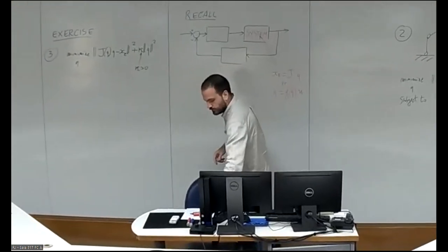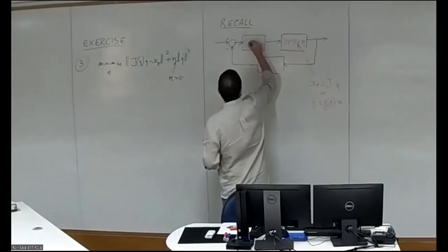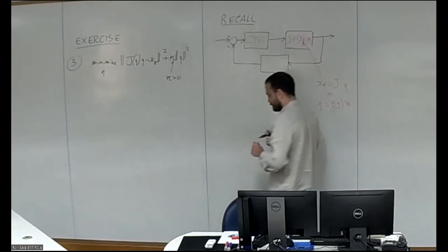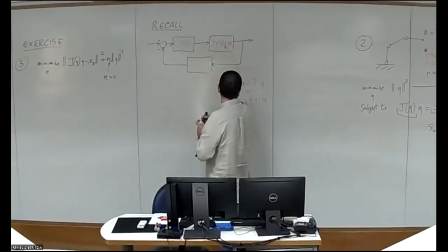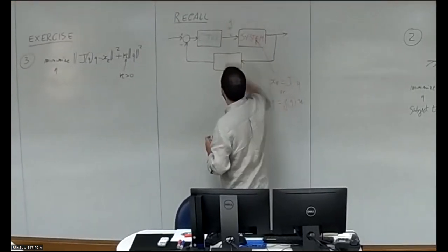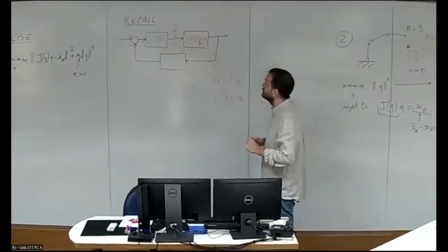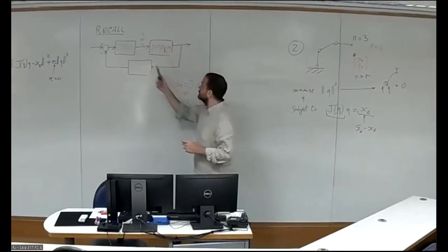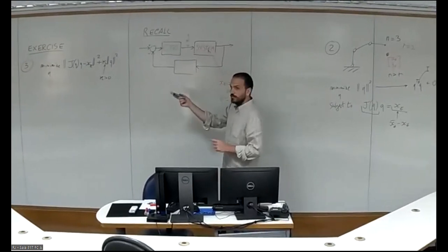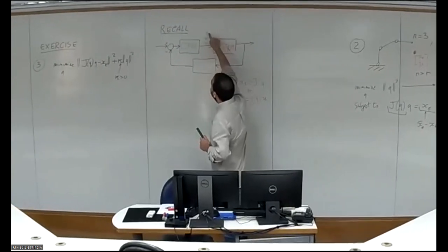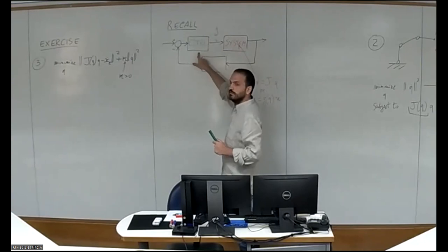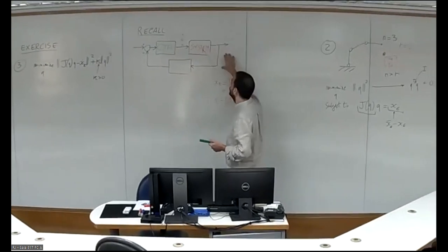And here is the controller. The controller gives as output a q dot for the manipulator or a u for the mobile robot. And this is exactly what we did, right? For the case of exercises 1, 2, and 3, we computed a q dot, specifically for manipulators, based on the state or the configuration of our system.